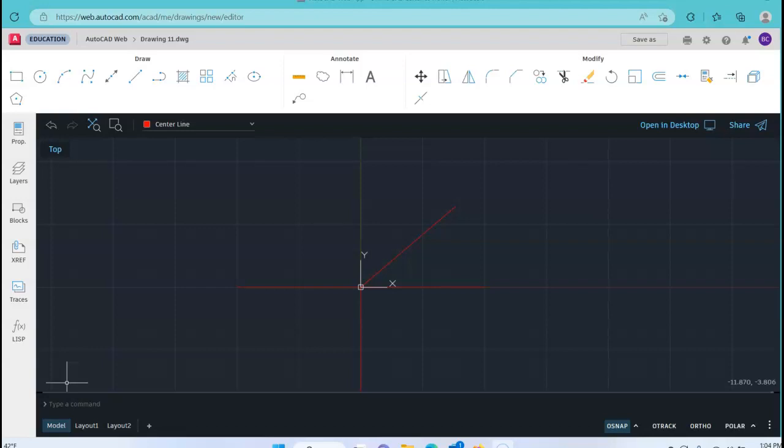All right, so now we have some basic center lines drawn in there to help us with some construction here as well. And the one other one in this version of AutoCAD, using the arc command is probably not the easiest method for us right now. As you look on the print, we do have another center line that's coming with a radius of 3 inches off of the center line. And probably the easiest way for us to generate that right now is just to use the circle tool.